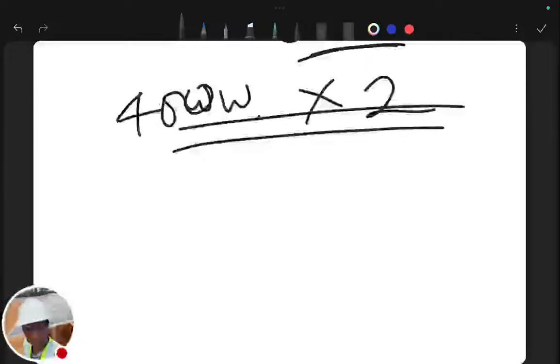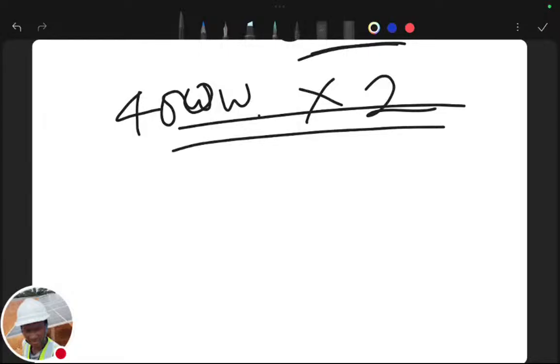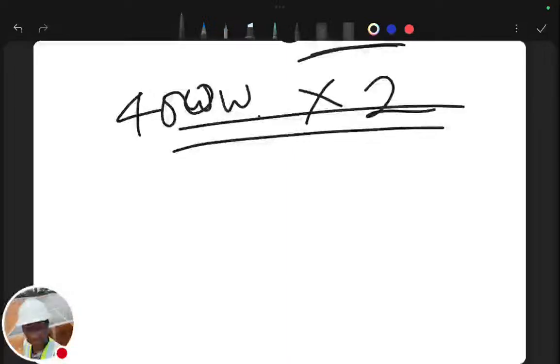But the main issue with it is your controller. A customer that could not afford 4 batteries or 2 batteries, that told you to use 1 battery, will probably not be able to afford an MPPT controller, which means you will probably be using a PWM controller. Oh, yeah, that reminds me, after this, we'll figure out the rating of the controller. But you know that the person will be using PWM because the person couldn't afford multiple batteries, right? If the person can afford an MPPT, go for it. But the person will most probably be using a PWM controller.